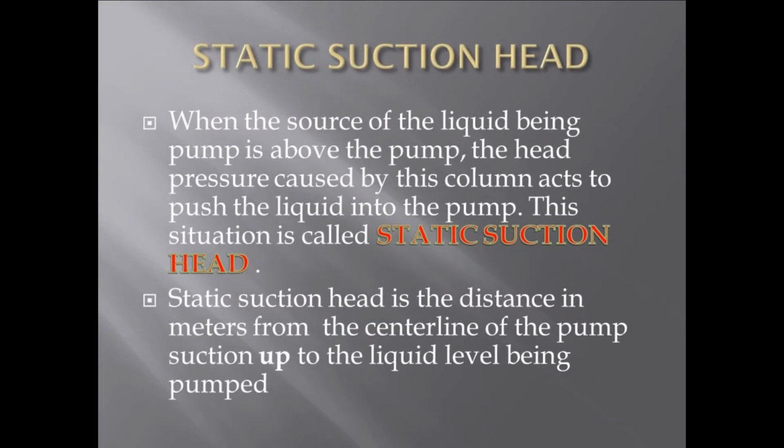Static suction head. When the source of the liquid being pumped is above the pump, the head pressure caused by this column acts to push the liquid into the pump. This situation is called static suction head. Static suction head is the distance in meters from the center line of the pump suction up to the liquid level being pumped.